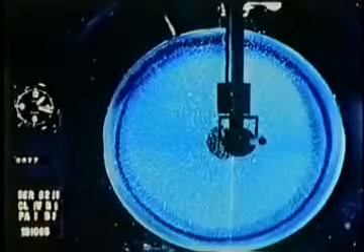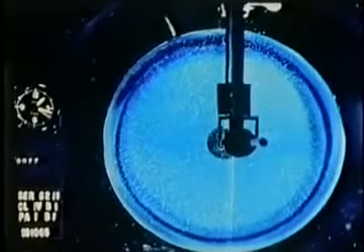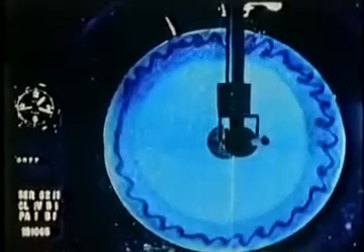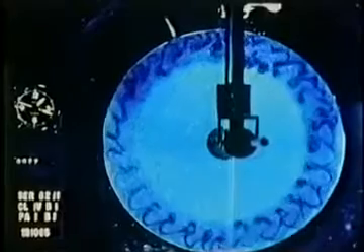The reason is that the rotational stability acts mainly against radial displacements. These become small relative to axial displacements as the rings decrease in width. We now increase the amplitude of oscillation. You see the onset of one of the spontaneous instabilities for which rotating fluids are notorious.